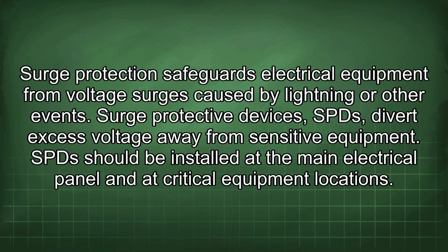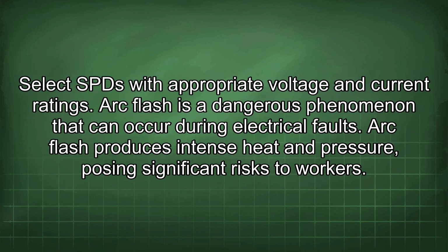Surge protection safeguards electrical equipment from voltage surges caused by lightning or other events. Surge protective devices, SPDs, divert excess voltage away from sensitive equipment. SPDs should be installed at the main electrical panel and at critical equipment locations. Select SPDs with appropriate voltage and current ratings.